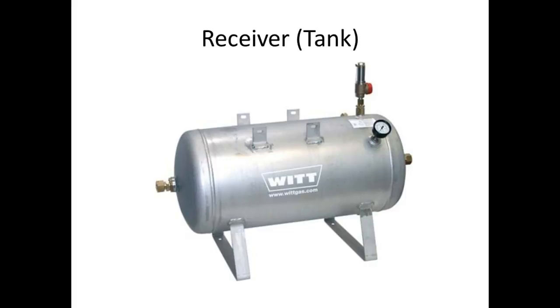If it was flat, then that 90 psi would be pushing against this flat area up here, right? But if everything's rounded like this, then they're pushing at different angles. They're not pushing in the same direction. So that means our walls can be a lot thinner.